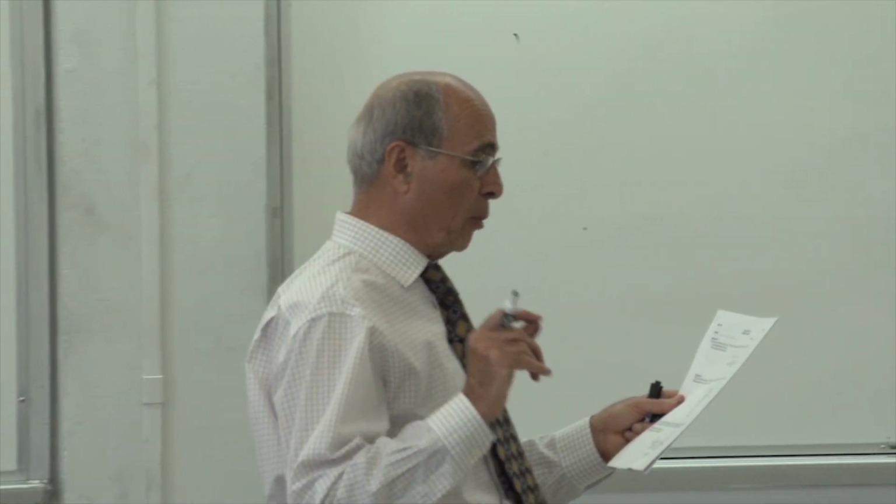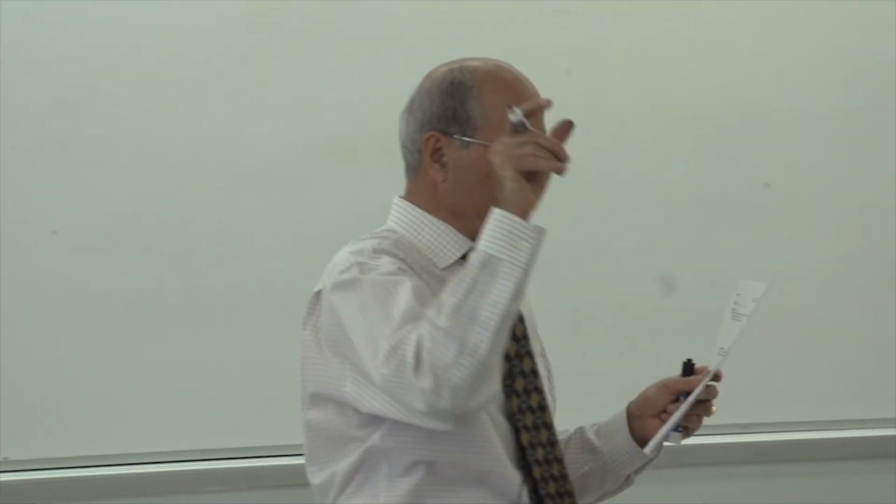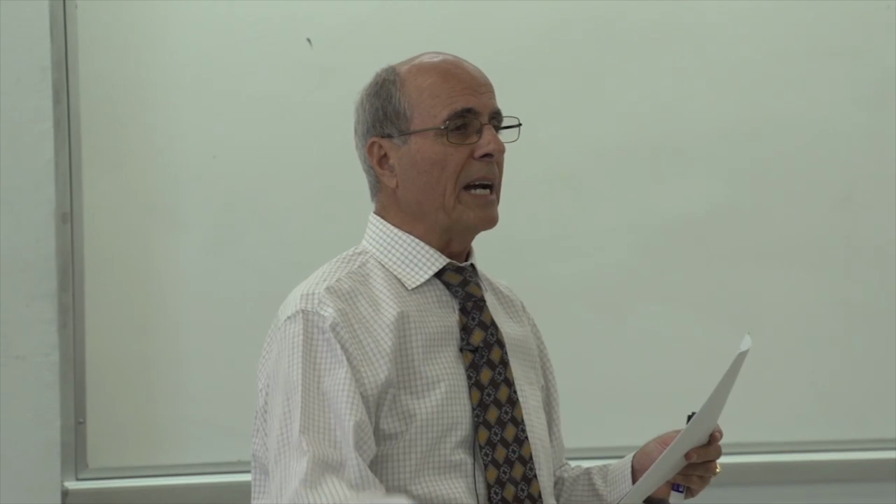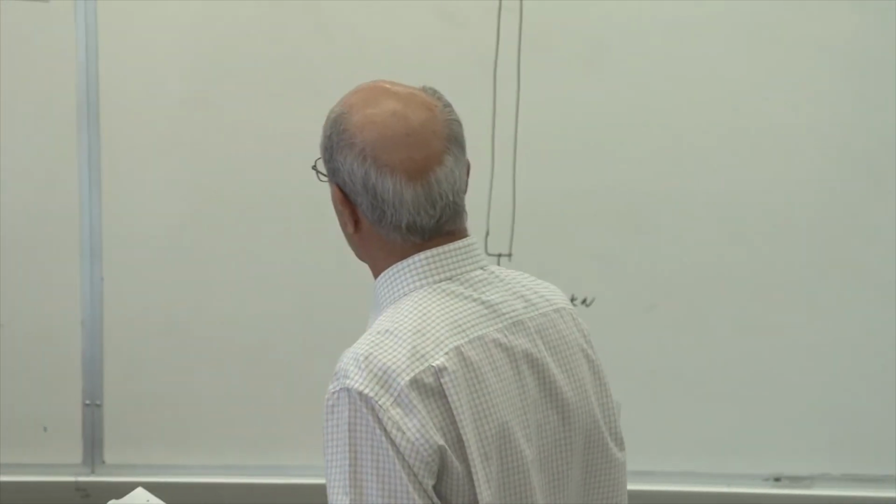What's the length of the rod? The length of the rod is not 400. The length of the rod is from point A to point B. There is a little plate there on top. Is that understood? I made it a little bit larger. Okay, can you calculate the delta? Yes, delta equals PL over EA. Point A is going to go down. But the rod is under tension. Is that it, or did something else happen?